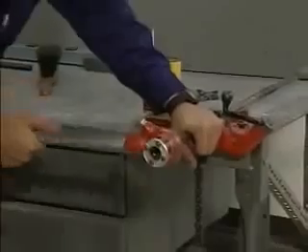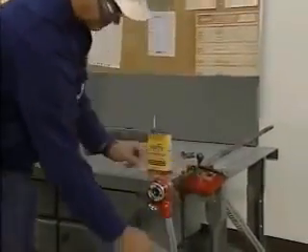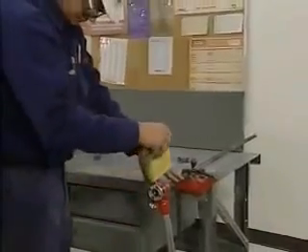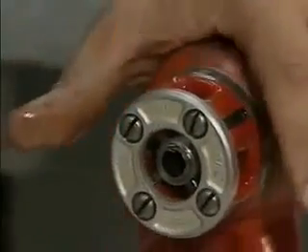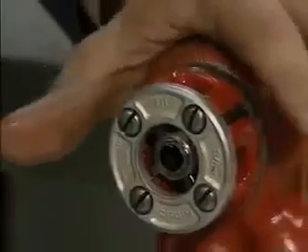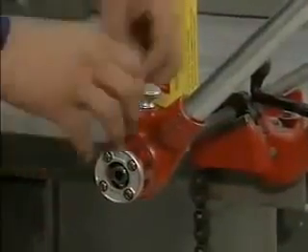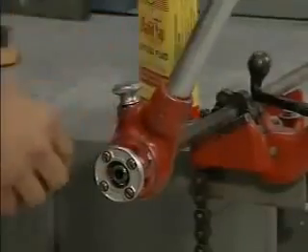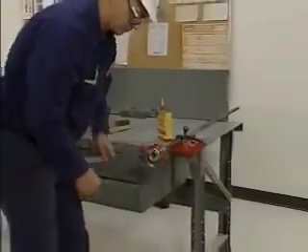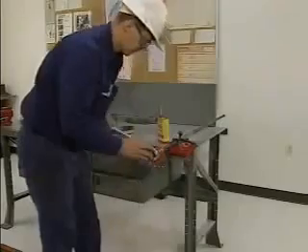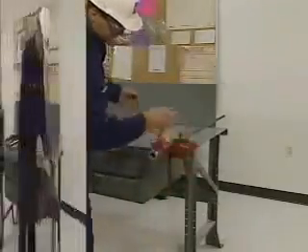Once the teeth of the die grab the pipe, you can continue turning the die without having to press it against the pipe. It may be necessary to apply additional cutting oil after a few turns as well. The pipe is fully threaded when 2 or 3 threads appear on the outside of the die. At this point, you can back the die off the pipe by reversing this knob on the ratchet. It may be necessary to move the die back and forth on the pipe as it is being removed. This removes some of the metal chips and ensures that the threads are not damaged.